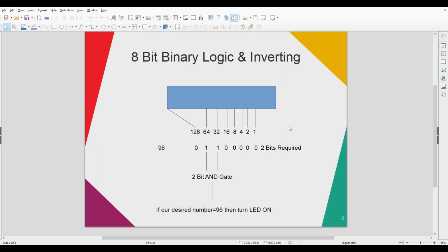So in the case of the video logic we're looking at now, this would be maybe the front porch or the back porch, horizontal sync or the vertical sync for what Benita was trying to do. What we're trying to do is just determine what type of logic we need, and the simplest way of doing it is to say, okay, I've reached the number 96. When I've hit 96, I want to reset my counter and we'll carry on. So in this case, 96, very easy.